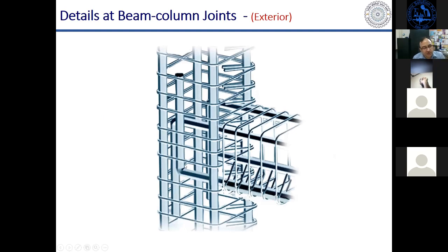Now, in addition to shear reinforcement, in any case we have to provide confinement within the joint also. So both the codes, IS 13920 as well as NBC 105, ask for this confinement. No, sorry, I was mistaken. NBC does not write this explicitly.